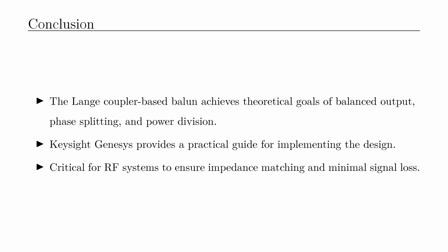In conclusion, the Lange coupler-based Balun successfully achieves its theoretical objectives of balanced output, phase splitting, and power division. The scattering parameters S21 and S31 validate its performance. Tools like Keysight Genesys facilitate accurate implementation, making this Balun design invaluable in RF and microwave systems.